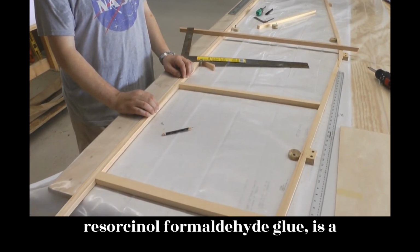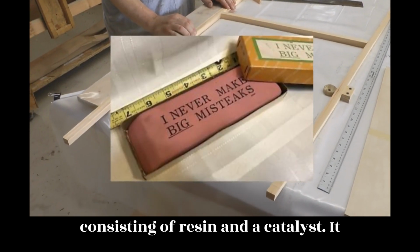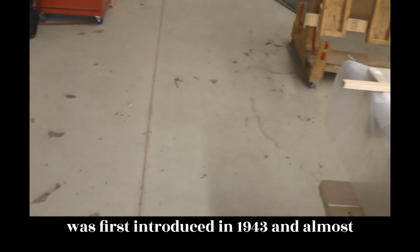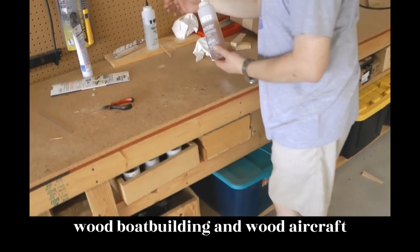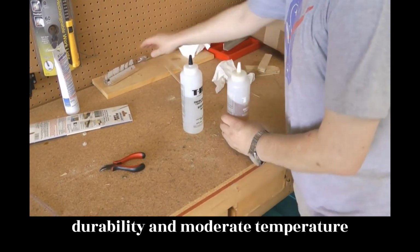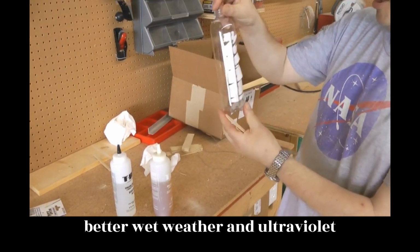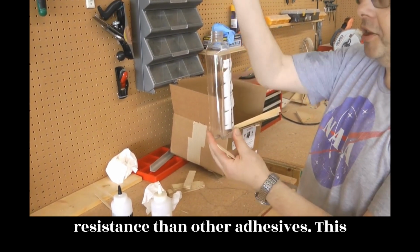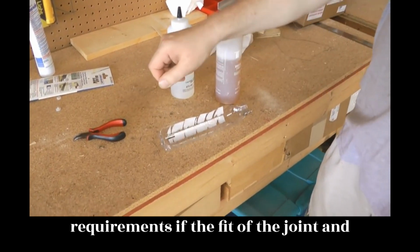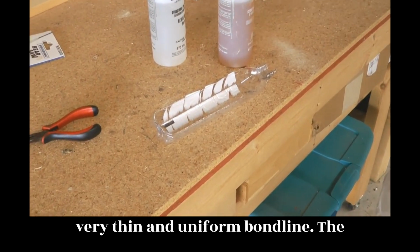Resorcinol glue, or resorcinol formaldehyde glue, is a two-component synthetic adhesive consisting of resin and a catalyst. It was first introduced in 1943 and almost immediately found wide application in the wood boatbuilding and wood aircraft industry, in which the combination of high durability and moderate temperature curing was extremely important. It has better wet weather and ultraviolet (UV) resistance than other adhesives. This glue meets all strength and durability requirements if the fit of the joint and proper clamping pressure result in a very thin and uniform bond line.